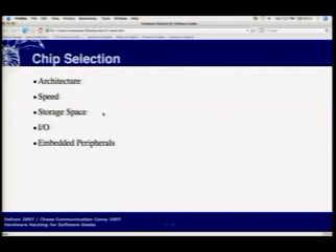A lot of microcontrollers have moved to system-on-a-chip architectures, where you've got not only the CPU core, it's called, which is the core that determines what instruction set it uses, but also standard peripheral systems. So you're going to have like an SPI module, maybe a couple CAN modules, which is a proprietary communication protocol, which is very common in automotive, marine, and avionic applications. You've got SPI, of course, which is another standard interconnect for other devices, which may be Ethernet chips or whatever. And then you've got EEPROM that might be off-board as well, off-board RAM that you've got to interact with.